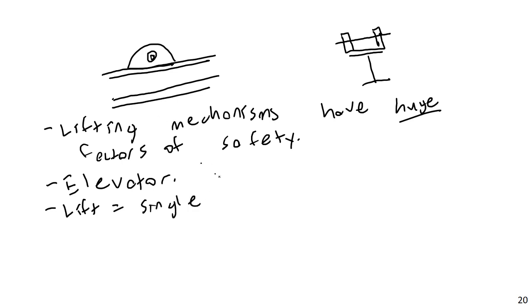Often, especially things like pad eyes. Normally in structures, there's a great deal of redundancy. So if one member fails, load can be passed on to another one. You might get yielding damage and excessive deformation, but usually you can avoid collapse just by spread of load.